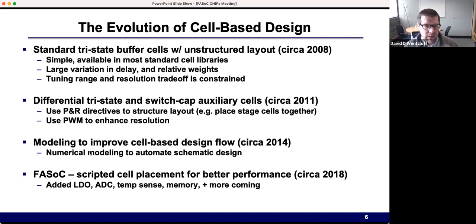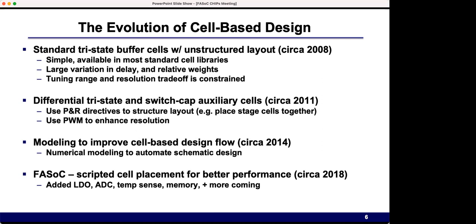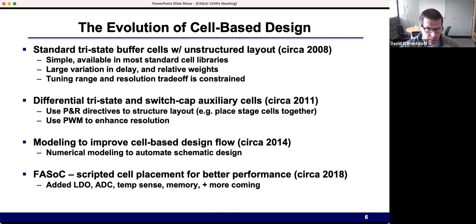All right, then we started looking at modeling, because now getting back to the earlier question about behavioral modeling, these circuits were getting more and more complex, bigger and bigger. We wanted to synthesize the analog circuit with the digital stuff around it. And then we wanted to know the performance post-PEX. After layout, we wanted to extract all RCs and then resimulate. And that was getting a bit cumbersome. So we started looking at modeling and ways to improve that design flow.